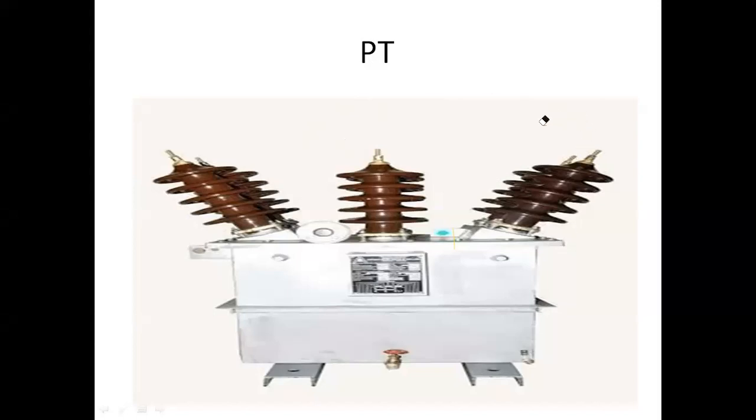But if we use our normal meter, that is an analog meter or digital meter, it is not capable of handling so much voltage. So we need to step down the voltage level. Say we are using the 11 kV line, then also we have to use this. But this is generally a step down transformer. PT is nothing but a step down transformer. This is called a potential transformer. Just remember, this is the potential transformer. Lots of questions are asked from this PT and CT.